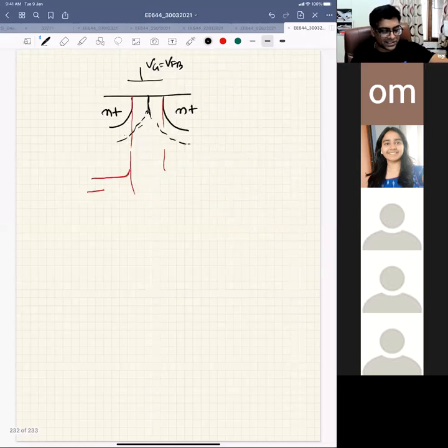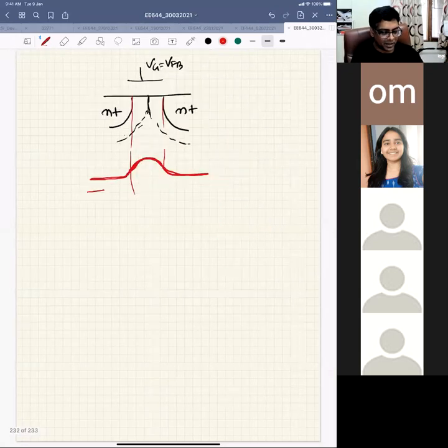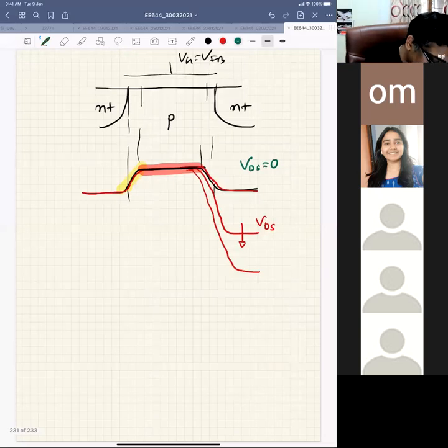But in this case, since Vg equal to VFB, there is some charge. So you will see your band will be something like this, right? There will be no flat region left. You could even see this will typically happen, because if you go on reducing the gate length, your EC will behave like this. The length is becoming shorter, right?